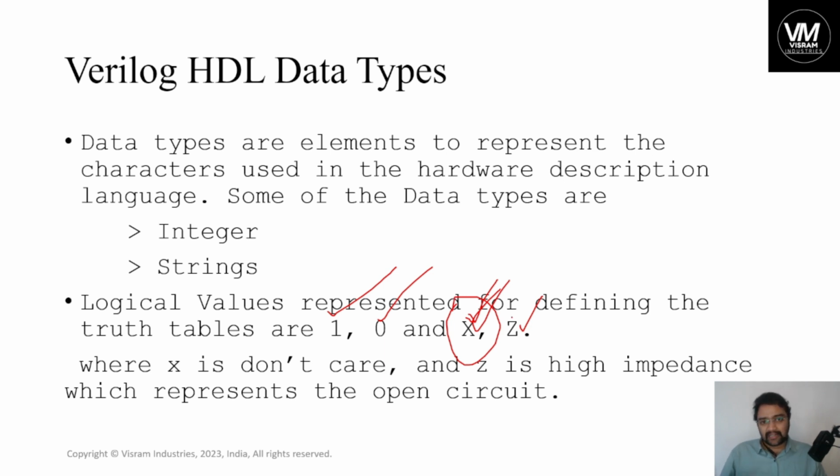The other kind is leaving the port in an open circuit. For example, you have a 4 by 1 mux and the ports are A, B, C and D. A is 1, B is 0, and C and D can be any value, 1 or 0, it doesn't care, because you are not selecting the C port and D, so now it is open.